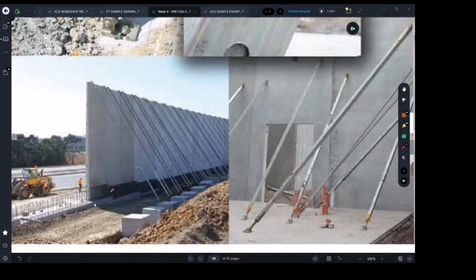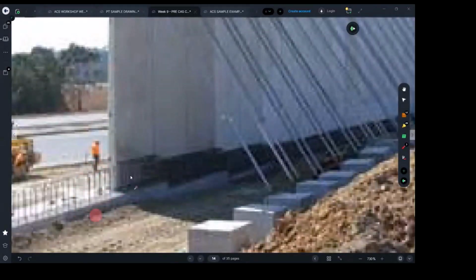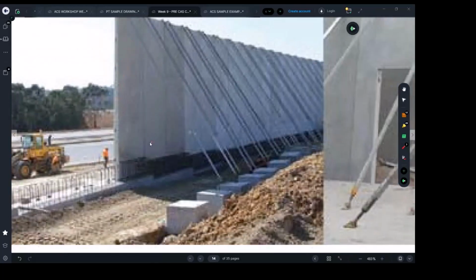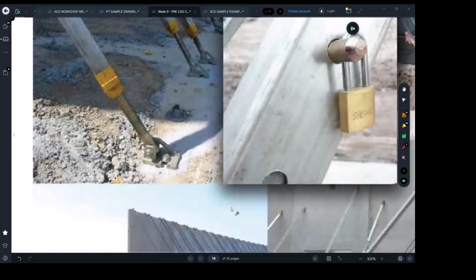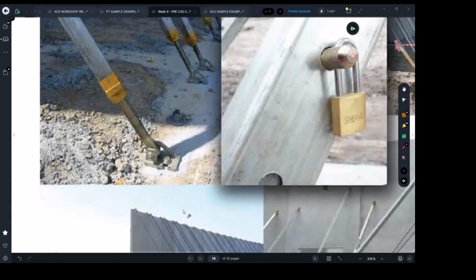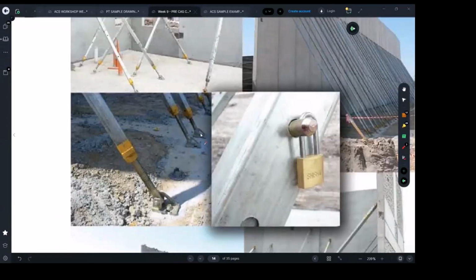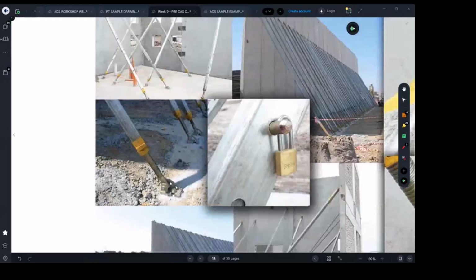This picture here shows you the casting bars, the starter bars that will house the panels, which we will see more about in such details in the engineering drawings. So you can see here they had some strip footings, whether they're going to be permanently used or they were just temporarily done. These strip footings, if they need to be done temporarily, will be really low-grade concrete, just for supporting that wind load. They won't be very heavy.